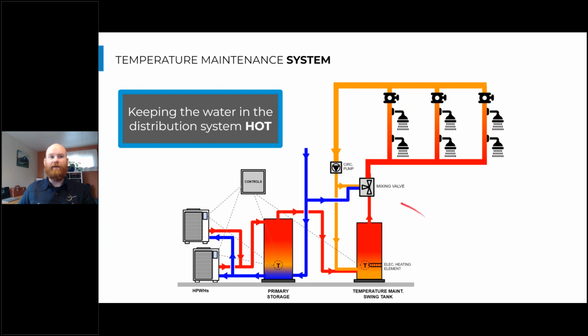So we might have our domestic hot water heating system in the basement. We might have a large 2-inch hot water main going across level 1, and then multiple maybe 1-inch, 3/4-inch risers that go up. They serve a bunch of units, 2 showers in this example.